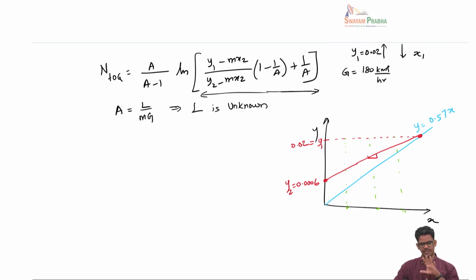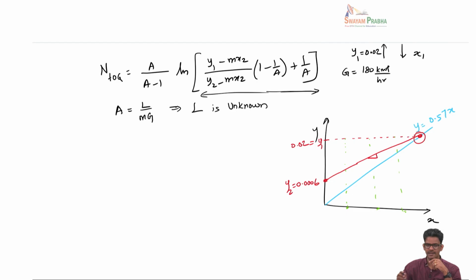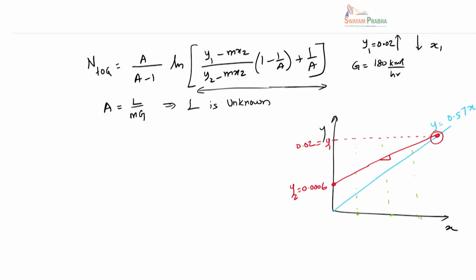Now you can do this, but be a little bit careful about this. Let's say you find this LS minimum and then you go to calculate A. I call it A minimum, right? And then if you go to this logarithmic term, you will see this term will blow up, because when you go close to this point, the average driving force vanishes.